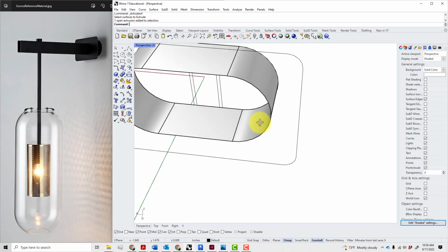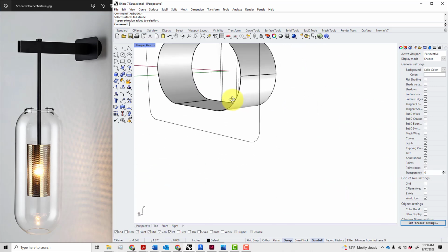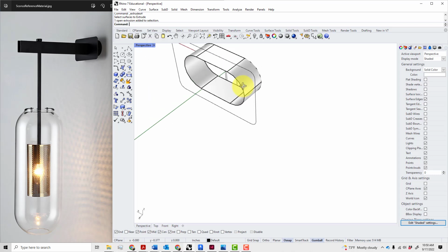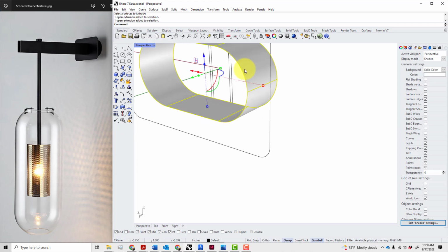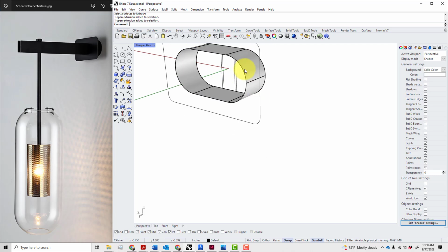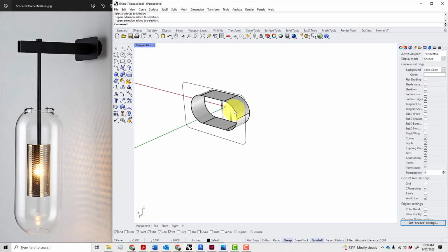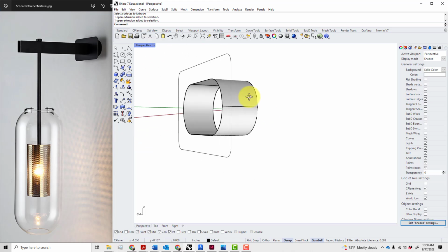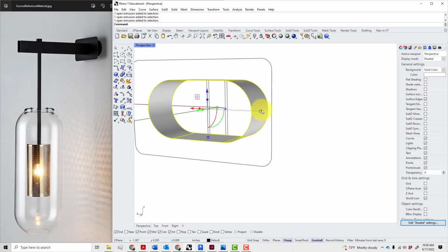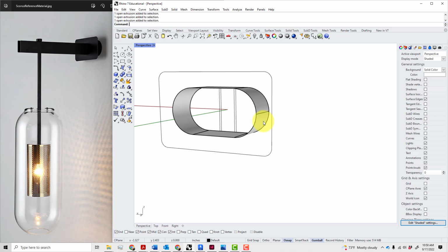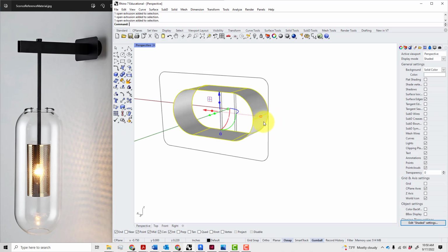What that means is that the surface obviously doesn't even have thickness, because I haven't given it any. I've just kind of rendered the surface. In some modeling software, that really doesn't even exist in the world until it has thickness. So I can give it thickness by, in this case, offsetting the surface, and I want to flip it.